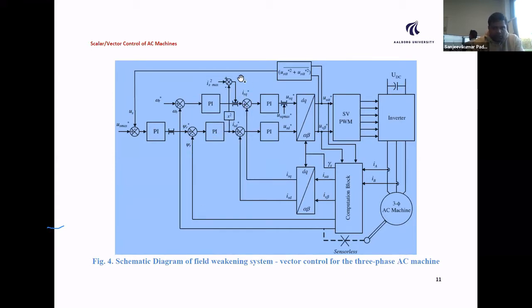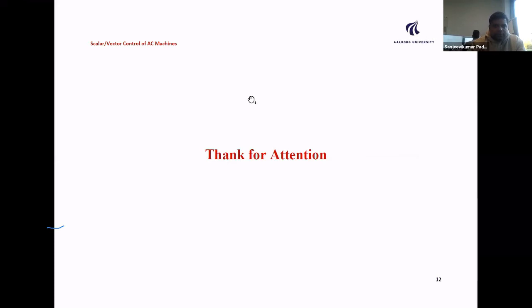Of course, we need to do this also for the stator current saturation. So the stator current saturation maximum value is taken and compared with the two feedbacks available here. So I have two values. I made Id because it's very important. Id is going to control the flux, which is the field parameter. It is squared and compared with the reference value, and this feedback error is fed here to calculate your torque. So in this way, you reduce the field weakening effects in your electrical machines so that you can have more dynamic vector control.